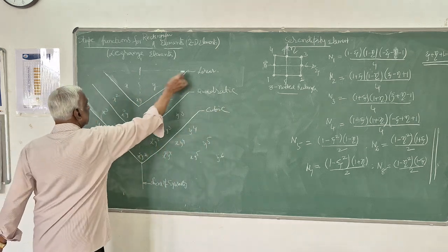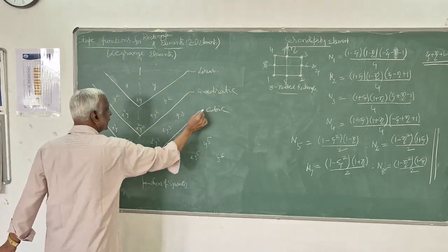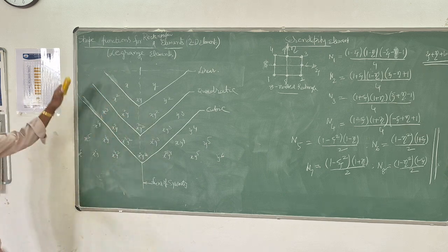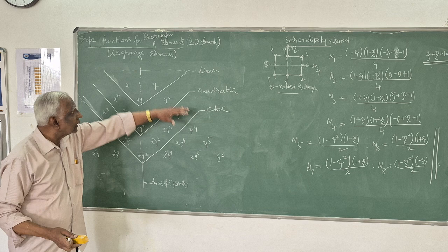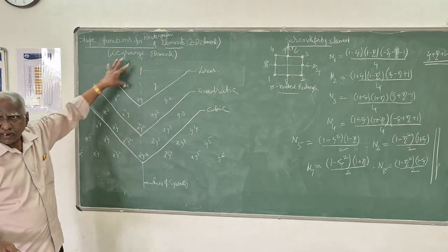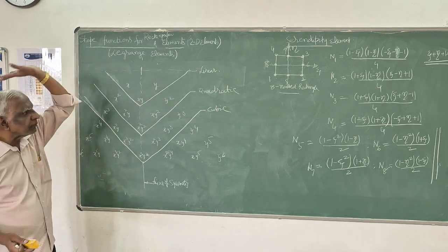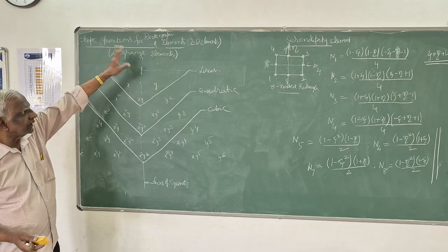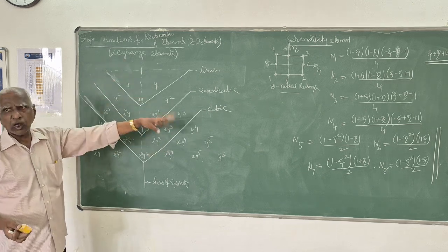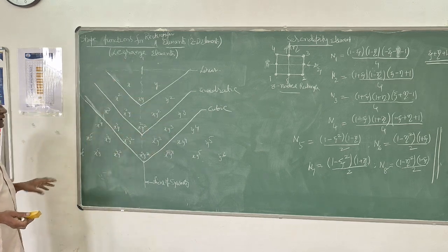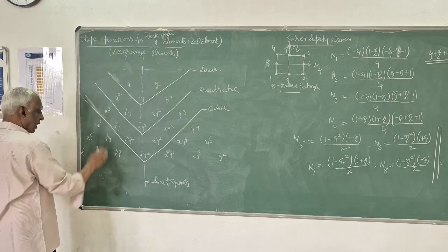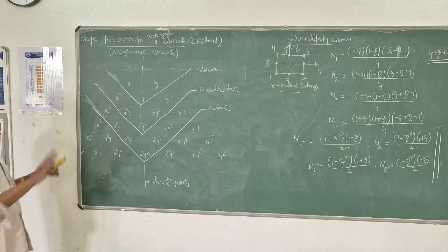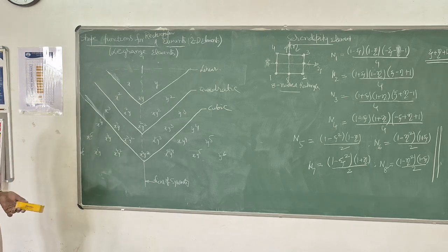All the terms in this third triangle are present. So you will find these elements are continuous as well as complete. All the terms will be present in the polynomial equation which we select for these elements.